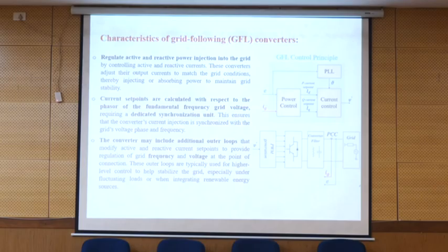If you consider the structure, it always follows based on the PLL, the theta coming from the PLL. There is a problem: when we go through the PLL and a fault happens, the control loop gets into a problematic situation. So we also need to consider some extra features in the control loop of the converter.